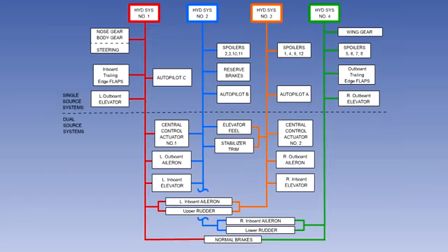Most modern aircraft will have multiple hydraulic supplies available for flight controls. 2, 3, or even 4 independent hydraulic systems can simultaneously supply power for the primary flying controls. On the Boeing 747, for instance, each primary flying control is split into 2 separate parts, and each part is fed by 2 hydraulic systems, so a pressure maintaining valve is not required.